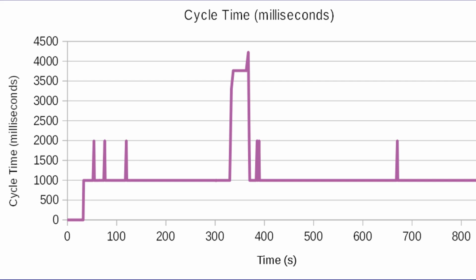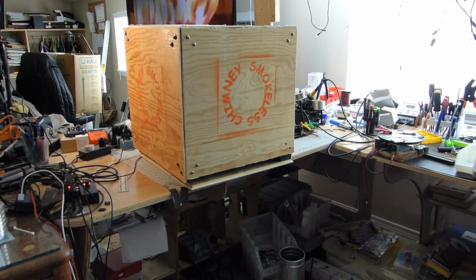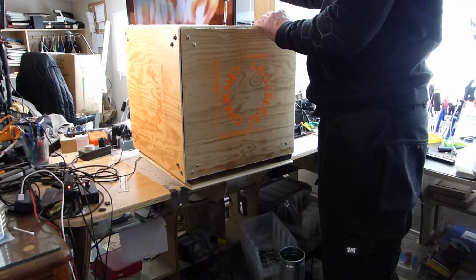But I do know that when I put a dark filter, a really dark filter, we're not letting much light into the sensor, and it takes longer to measure the light if there's not as much light. So the sensor responds quite slow in extremely dark light, and there will be a time delay or a time offset when this occurs. Next, we have a simulated unboxing.